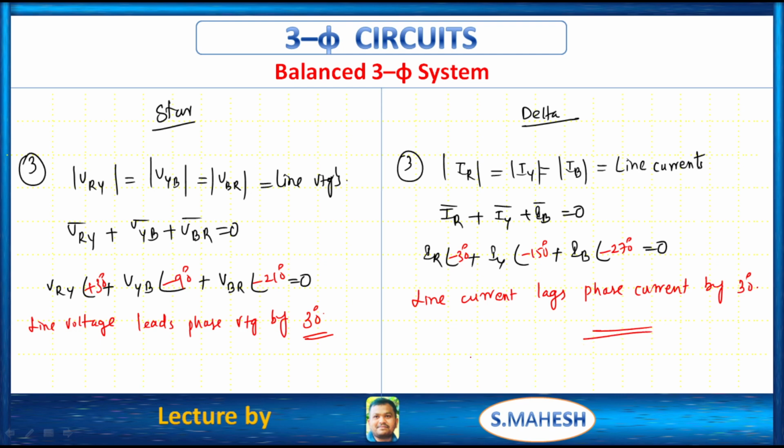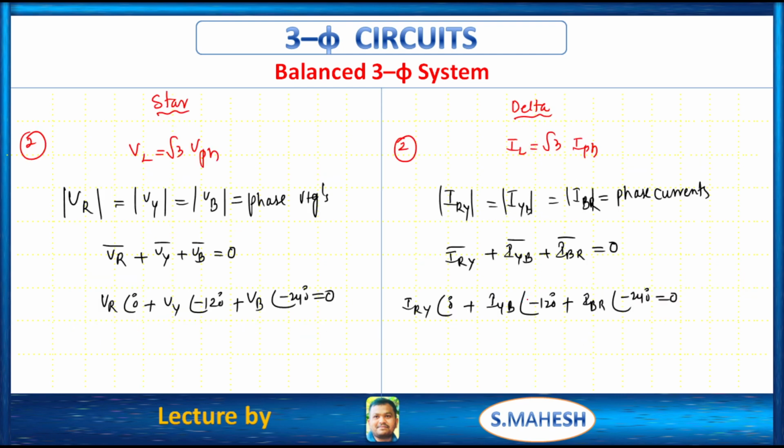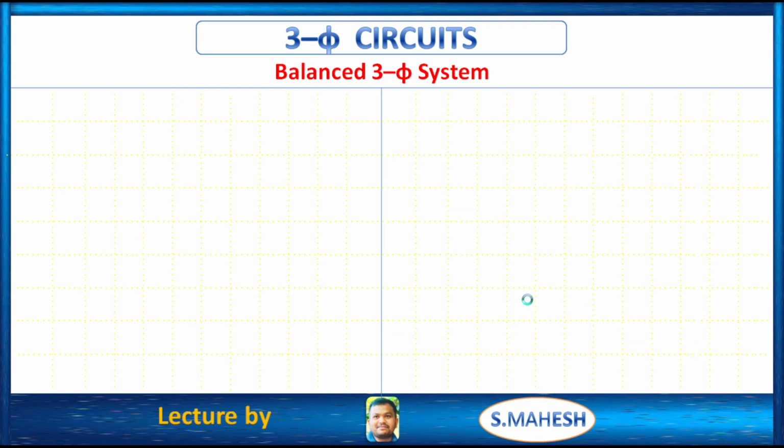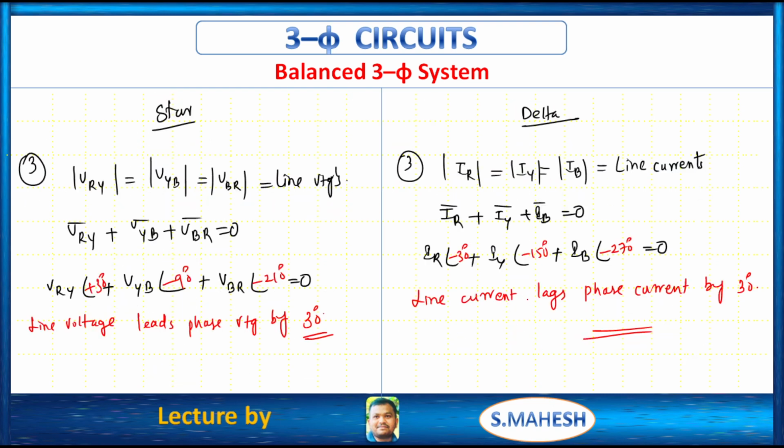This is the analysis of the three-phase system. Okay, these are the important summary points. So, how to decide whether the system is balanced or not? It totally depends upon the load, the three-phase impedance load. If the impedance is the same with respect to all phases, meaning all phases are displaced by 120 degrees, then only the load currents are balanced, then only the system is said to be a balanced three-phase system. Okay, that is, the summation of all quantities of voltages or currents should be 0, then only the system is said to be a balanced three-phase system.